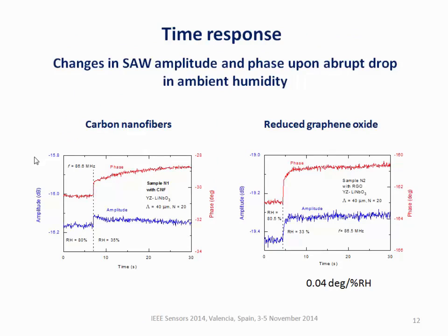And finally, the time response. If we make a humidity drop, that means if we change humidity in the chamber very fast, we see that the response of the surface acoustic wave is also very fast. It takes less than several parts of a second.